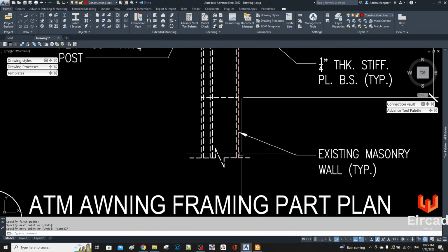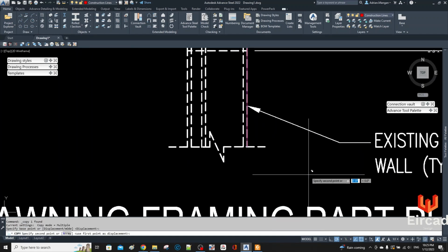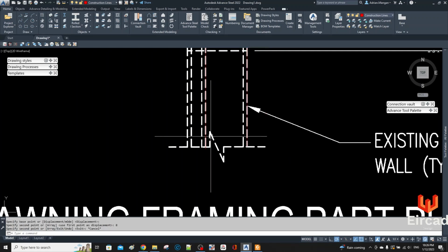Alright, so now we want to see how thick the wall is. I don't just copy it from this point to that point. I'll copy it kind of with a purpose. So I'll come over and see what it looks like. Now, obviously you can go and find out how thick the walls are and everything. Generally, I don't really get that information. So we can see that's probably going to be 9 inches. Unless I go to the inside one, that'd be 8. So let me go to 8 inches, probably 8-inch block.